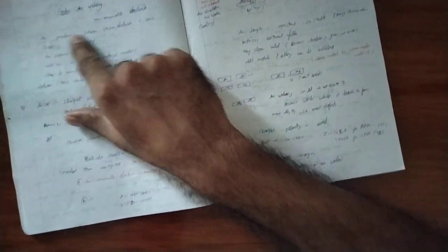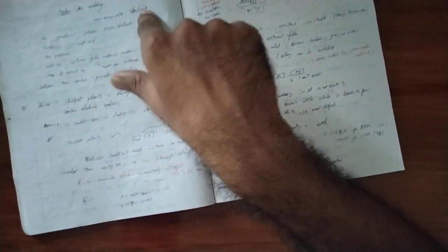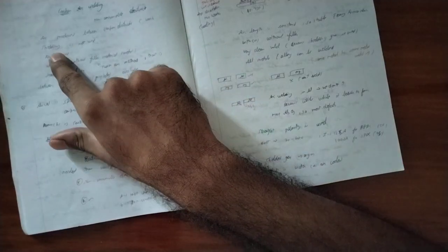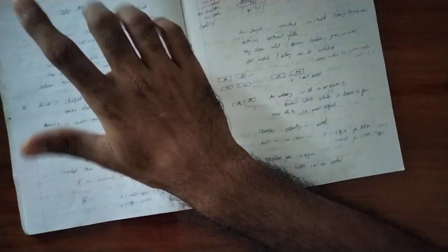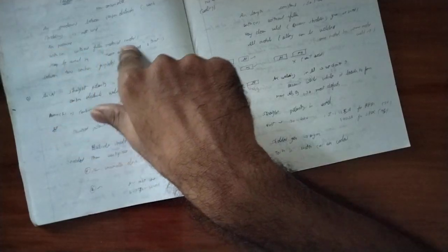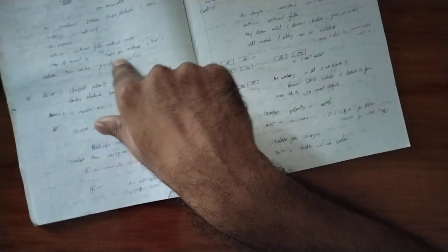Next is carbon arc welding. It uses a non-consumable electrode. The arc is produced between the carbon electrode and the work. Shielding is not used because it is a non-consumable electrode. No pressure is needed, and it can be used without filler metal. It may also be used in the twin arc method, between two carbon graphite electrodes.